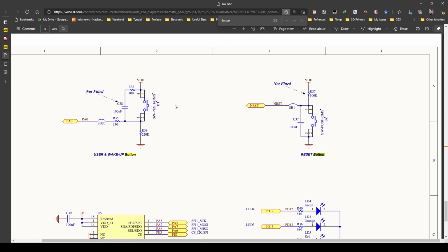When we press this button, 1 from here will go through this line, and when we release this button, there would be a floating state here which will be overridden by the 0 value here. So if we press the button, we receive 1. If we release the button, we will receive 0. So that's what we needed so far.